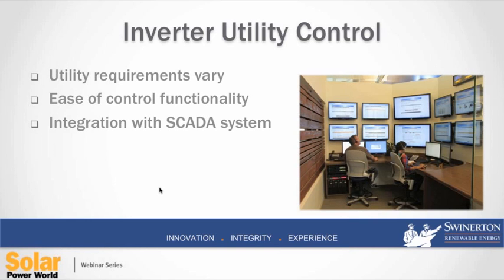There isn't a whole lot of voltage control or power factor control being asked of us. As we see requirements, especially in California with CAL-ISO type projects, the ability to curtail plants, control power factor, control voltage, and have set ramp rates already in place for the site to function based on what the utility wants is becoming more and more important. We're building out a more and more robust SCADA system and needing a more and more robust inverter to help us along with that process.